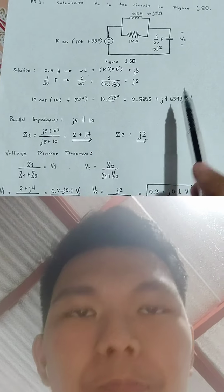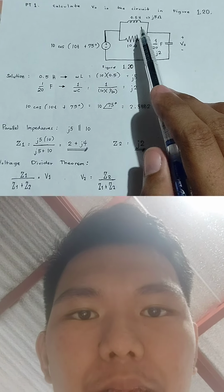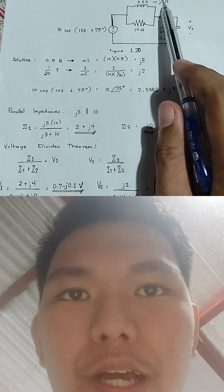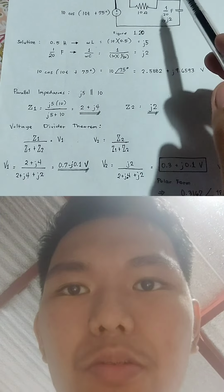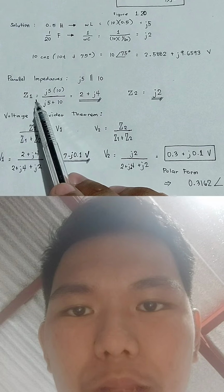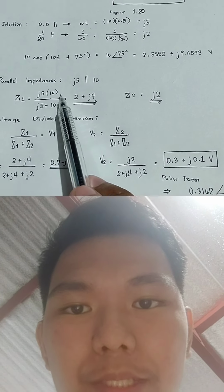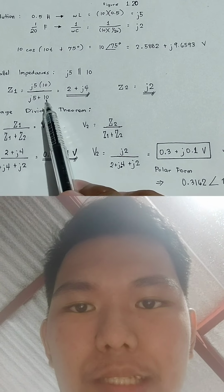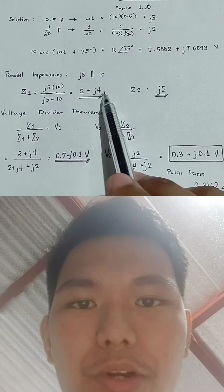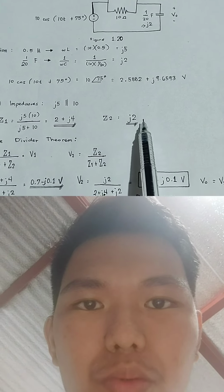Next, we will simplify this circuit. 0.5 Henry parallel to the 10 ohms, or the J5 parallel to the 10 ohms. For Z sub 1, Z1 is now equal to J5 times 10 over J5 plus 10. It is equal to 2 plus J4. For our Z sub 2, it is equal to J2.